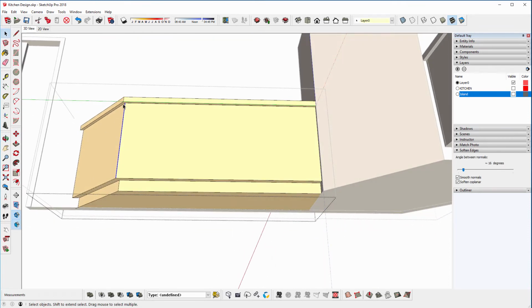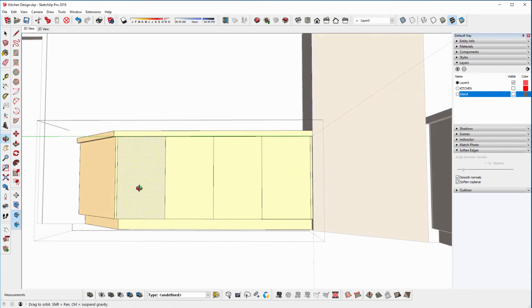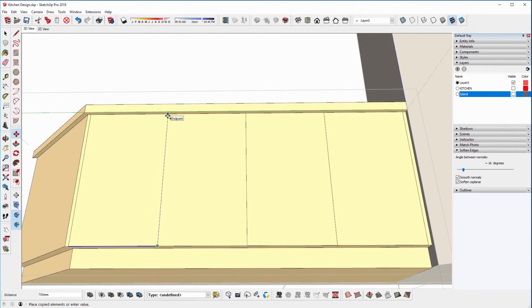So that is, you select the line you want to copy, get the move tool, press Control and copy it in 18. Do the same on the other end, select tool, move tool, then Control and copy it in 18, and then you can copy it to the end and you can tell it how many divisions you want, so maybe 4 divide, enter, and then again we could make one of these drawers again. So this time you might just copy it the whole distance from the bottom to the top, and then maybe 5 divide.